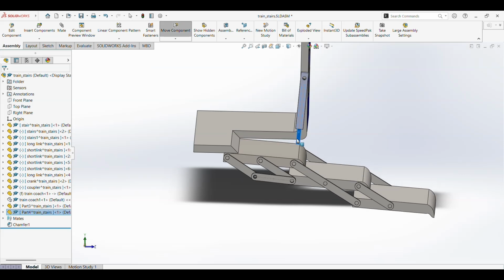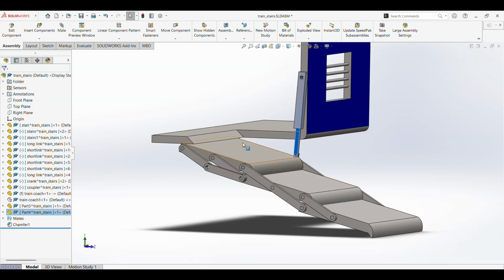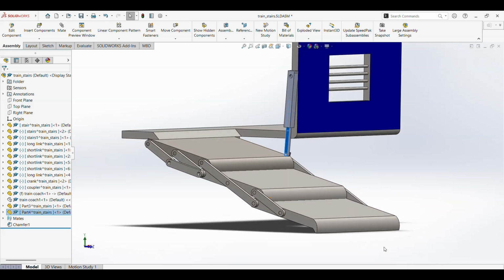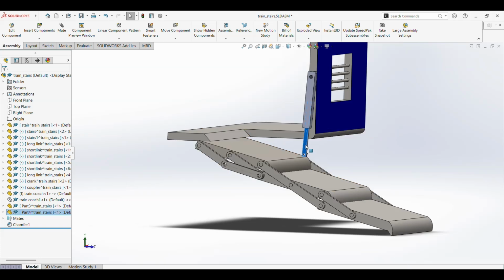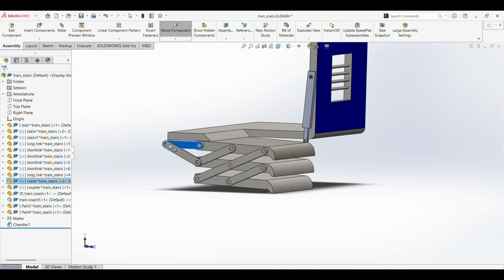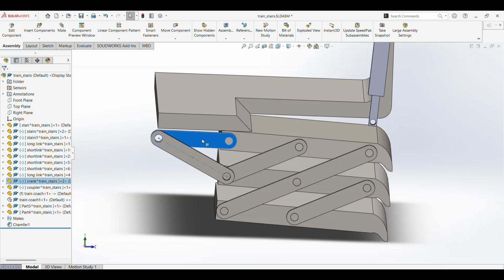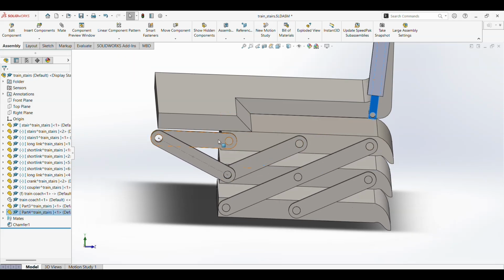So this particular actuator will move down the top of the ladder so that the entire stairs look like a ramp now. So it's much easier for things to move up and down through this. Once everything is done, the actuator will move up and the motor will be keeping everything down. After that, we will be keeping a solenoid valve here that will prevent the movement of this particular input link when everything is traveling, so that whenever the motor is powered off, the stairs don't accidentally go to the extended position.